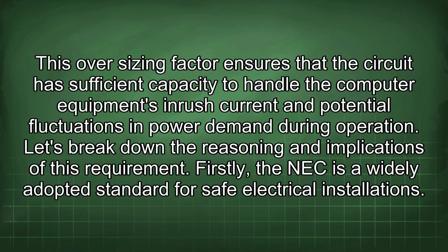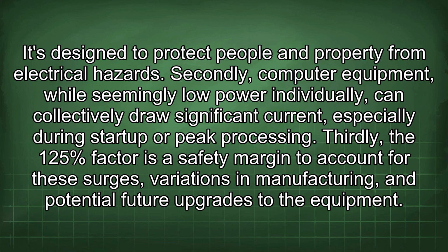This oversizing factor ensures that the circuit has sufficient capacity to handle the computer equipment's inrush current and potential fluctuations in power demand during operation. Let's break down the reasoning and implications of this requirement. Firstly, the NEC is a widely adopted standard for safe electrical installations. It's designed to protect people and property from electrical hazards.